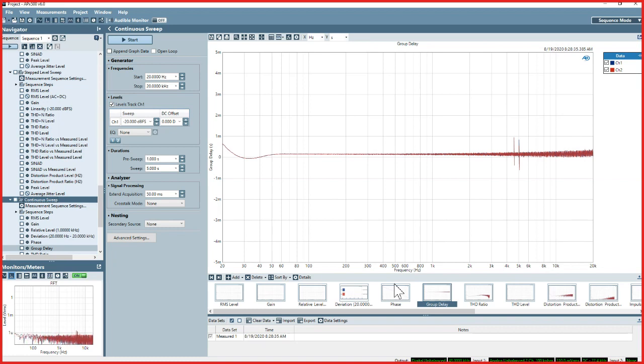I'd say that just generally, things we've seen that may cause errors in the impulse response is devices that don't have constant delay. Worst case imaginable might be a Bluetooth device where the actual delay of the device varies in time. Not having too much or too little delay. So in that particular case, I would suggest that we don't have an easy answer, and we should reach out to that person and talk about their specific device under test.